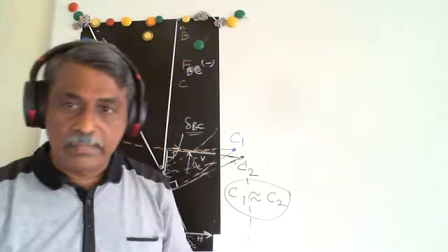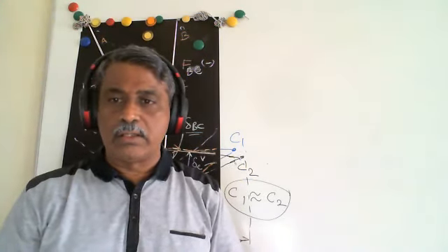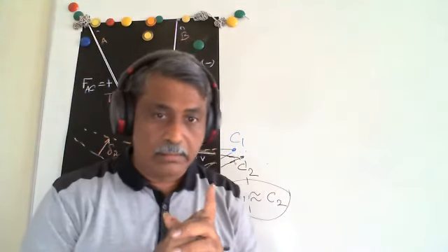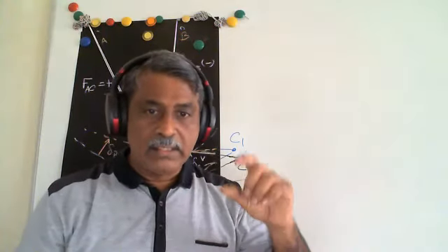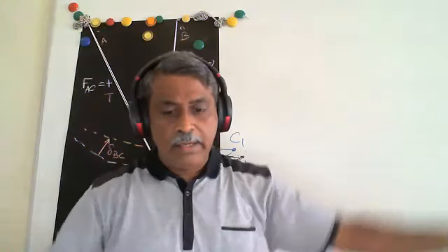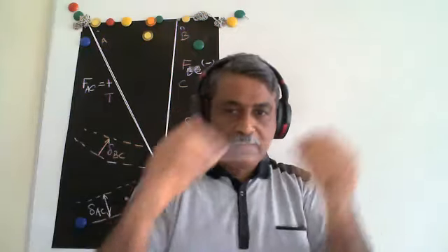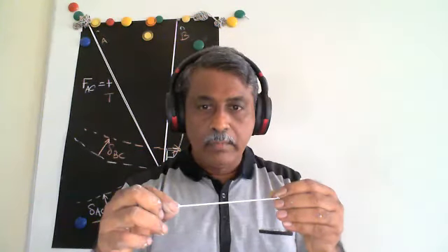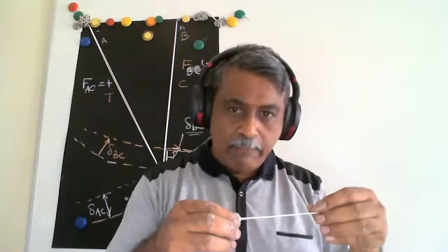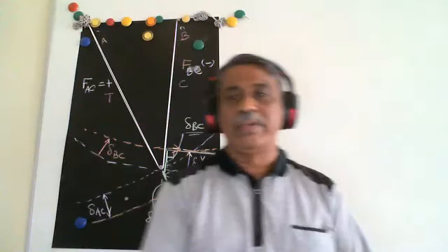Any questions? For what if all strains are small, but overall strain is not small compared to the length? No, remember it is strain, it is not elongation. It is strain, which means relative to the length. So if I take only 100 mm length like this, let's say it is deflected by 1 mm. If I take, let's say, 200 meters of this and apply the same force, it will elongate a lot. But the elongation compared to its original length is very small.